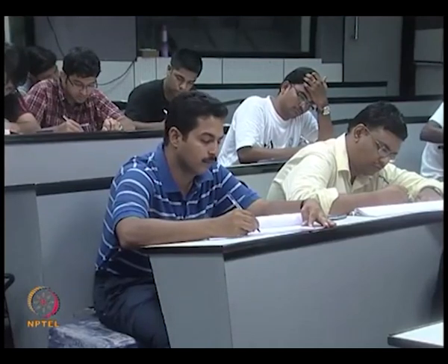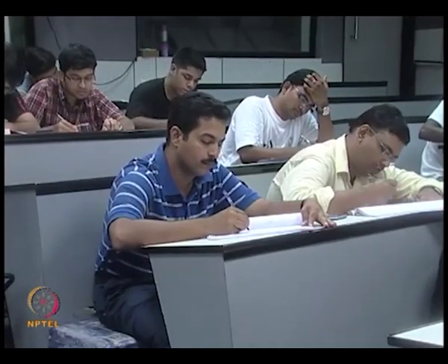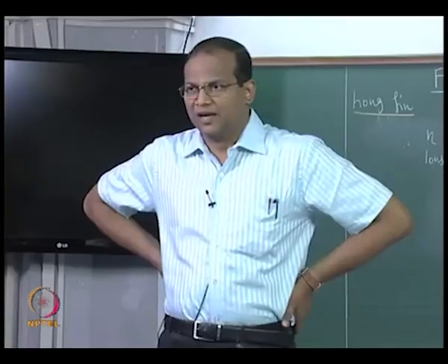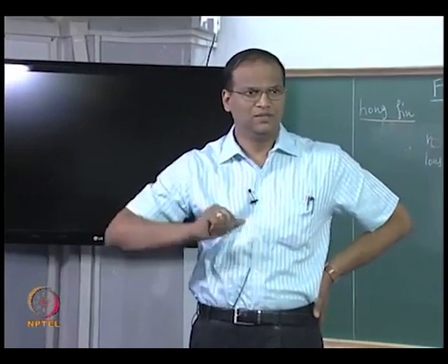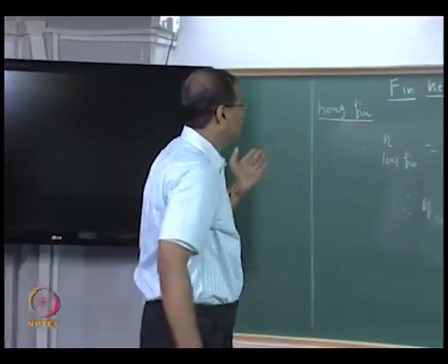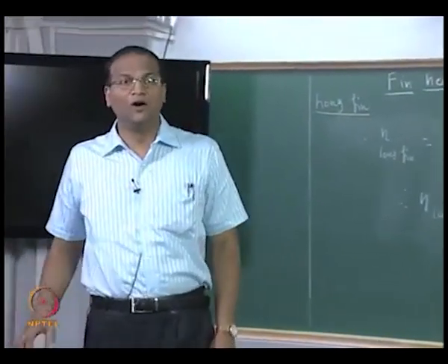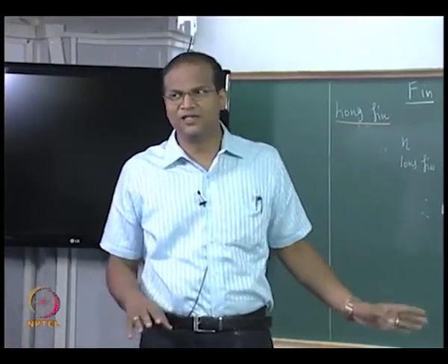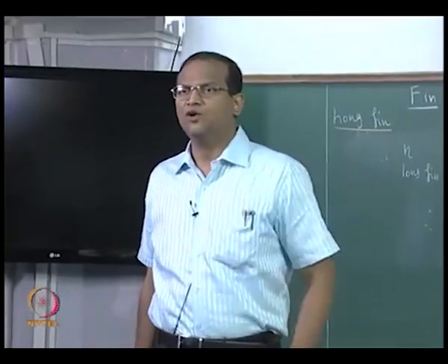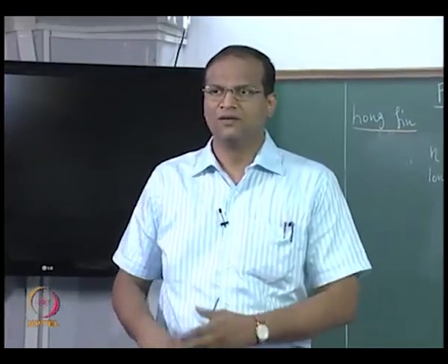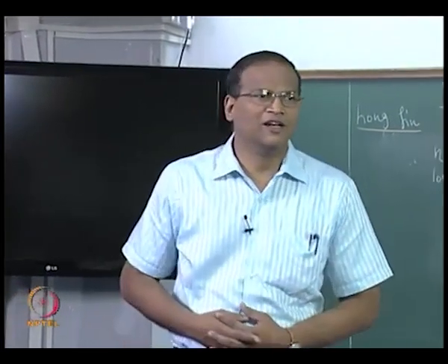It is a simple problem which gives you a practical aspect of the effect of a change in the geometry on the heat transfer performance of a fin, part A. Part B, what is the change in the material used in fins? I have already told you you have to look out for the buzzwords. A long copper rod, a long aluminum rod means it is a long fin, and it is attached to the base. You do not have to write the governing energy equation for conduction in cylindrical coordinates and try to solve it.